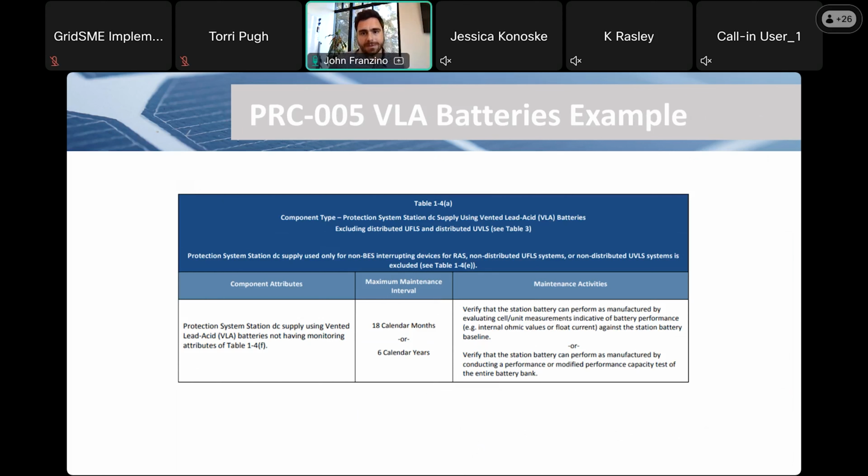Again, we're talking batteries on a quarterly basis, and thereafter, I want to say off the top of my head, the next most frequent time horizon is every 6 years. So it's good that you don't have to do much besides batteries every year. Bad, because since the time horizon is so long, it's easy to forget about. So you've got to make sure you have the right program in place to track this over a long duration and ensure that the required maintenance does get done at year 6 or at year 12, whatever it may be.